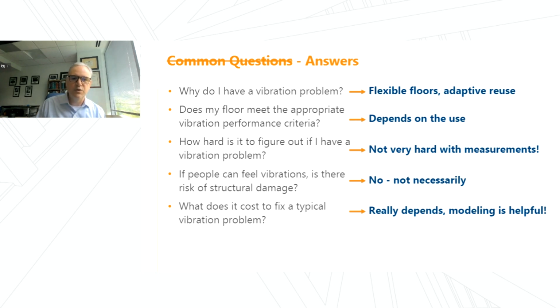The good news is, using a combined approach of measurement and modeling, we can simulate and evaluate multiple retrofit options before anything is built. Sometimes we can even test those cases on site, for example the TMD, before really committing to that retrofit solution. I think the point here is the measured, data-driven process helps clients make better informed, cost-effective decisions.